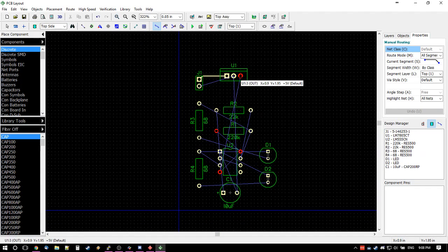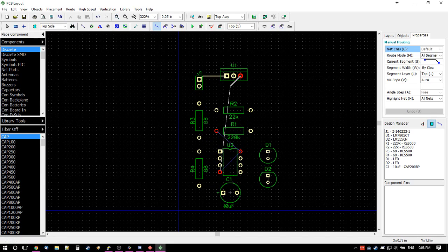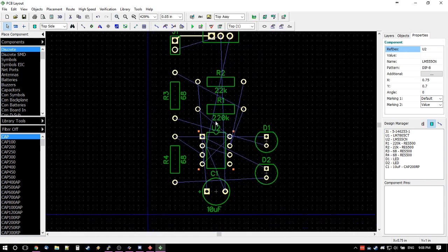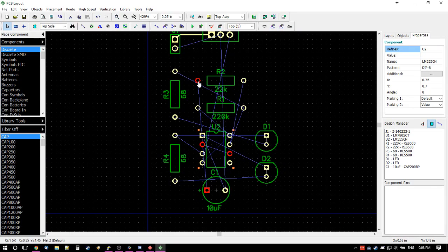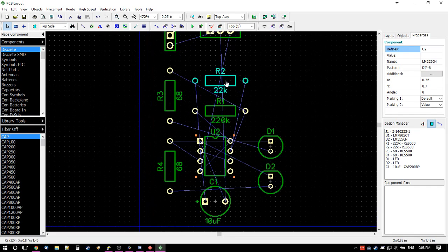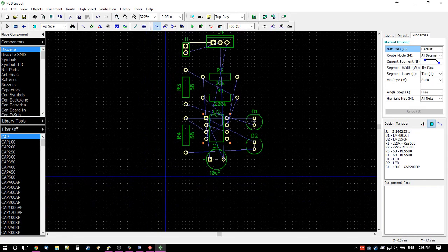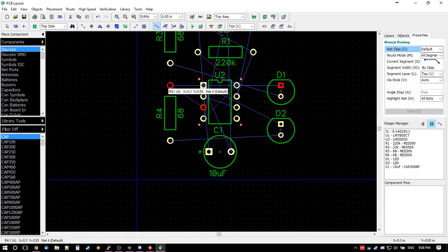Alright, so now the plus 5 volts, we're going to route that. Let's see. Yeah, let's route it. Let me take a look at the rat lines again. Okay, you know what, let's get the resistors and everything done first. So that way we'll know if we have to route our power around or if we can go through the middle. So we'll start off with some of the easy ones.